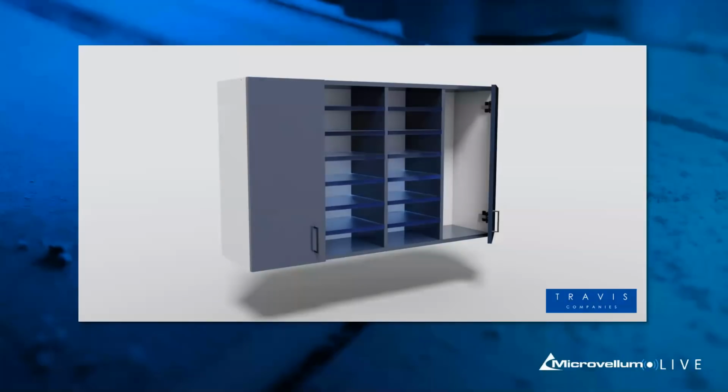Right. So what was the learning curve for you? It's actually not too difficult. If you know how to use product prompts in Microvellum to input your products, that's basically where you're going to be doing most of your work. You'll have options to select the number of bays you want in your product, and for each bay there'll be a tab up at the top of the prompts. You can choose whatever option you'd like. So it's familiar if you know product prompts, and it's great too because it draws as a regular product. If you want to see it, all you have to do is draw the product in 3D, and you'll see exactly what information you've put in.